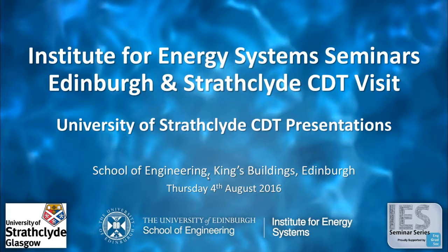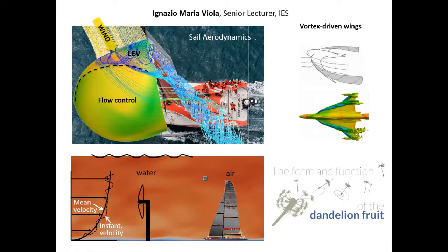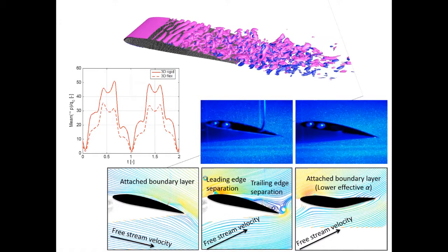I'll carry on meantime. So an example that I think is very relevant to you is, for instance, when this turbulent flow is actually interacting with the turbine. So there is vorticity in the flow, and there is vorticity which is generated by the turbine blade. The two vorticities interact and can be constructive or destructive. This interference might be extremely powerful.